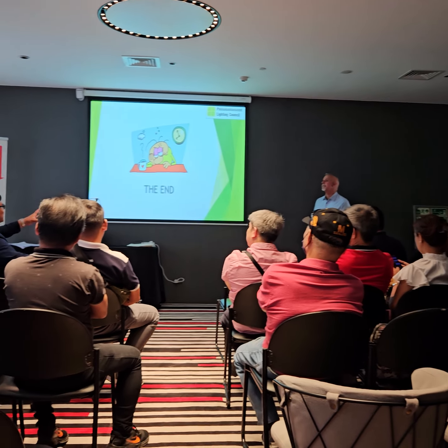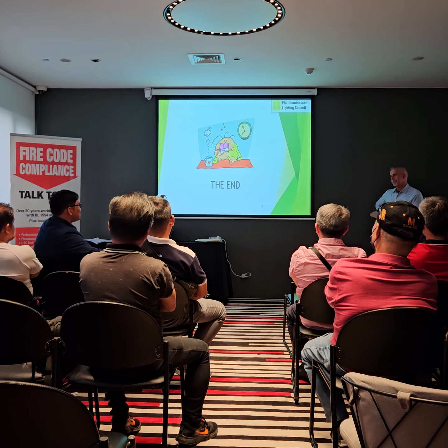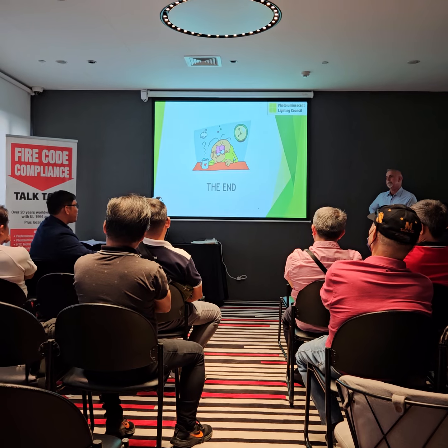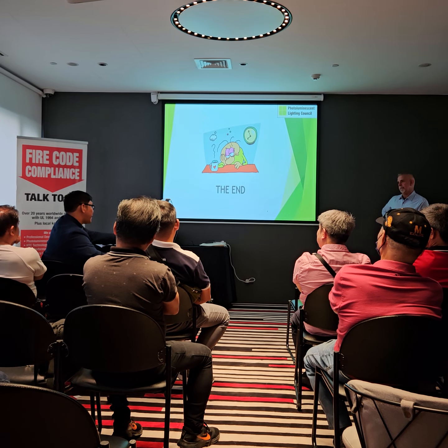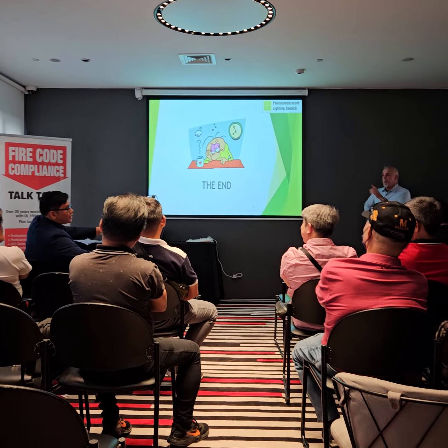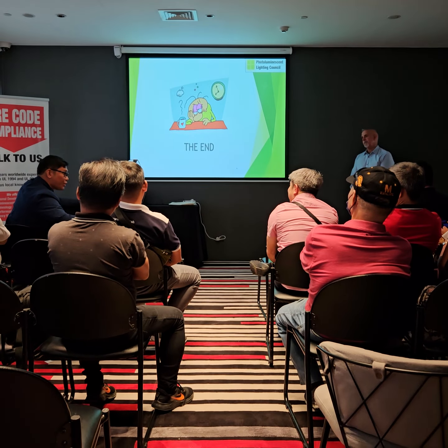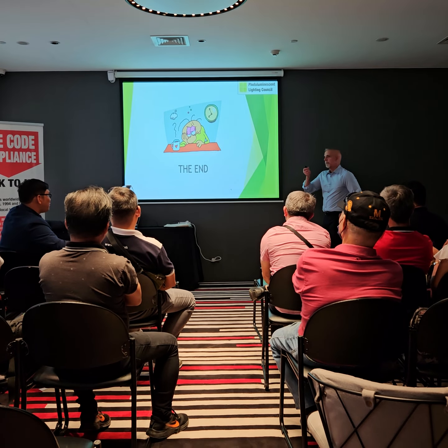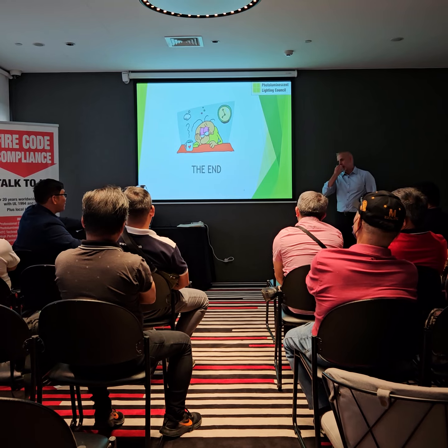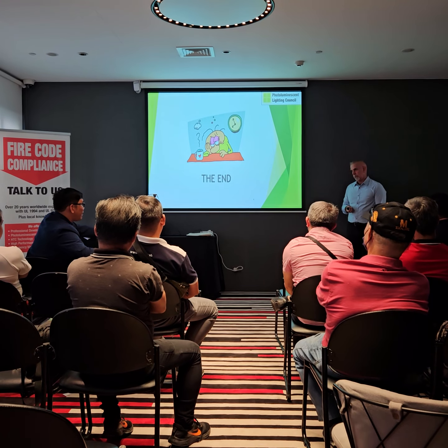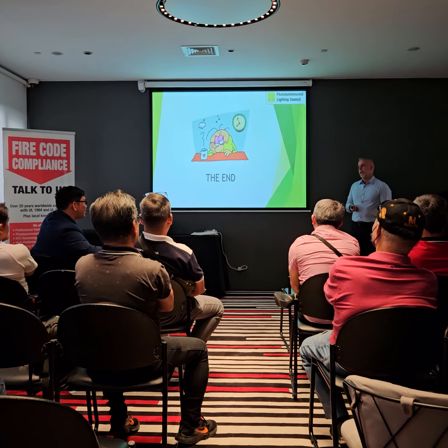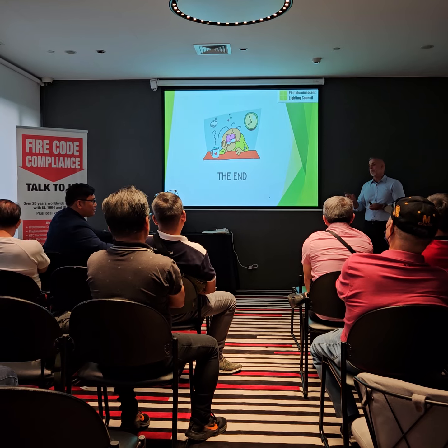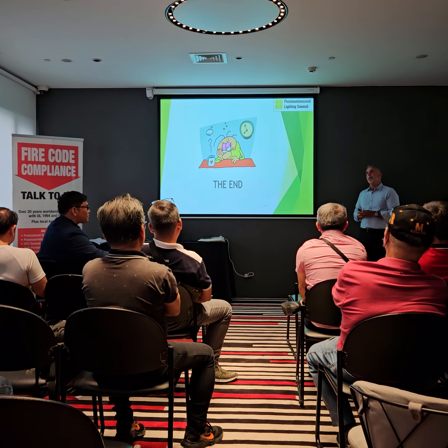Although there's a written standard, like 54 lux, from my experience, is that the minimum standard you have to meet when it's already installed in your establishment? Yes, in the building. So what needs to be proven is that you have a proper ASTM procedure on how you are going to test the 54 lux. There are a couple of different testing ways: the commissioning testing, the tools, the trained personnel doing the testing.